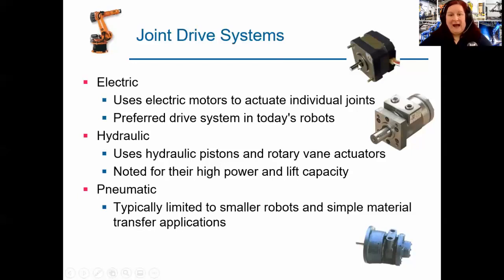So in terms of how we drive our industrial robots, we might have different drive systems. They might be electric, hydraulic, pneumatic. If we are lifting very, very heavy stuff, hydraulic is the way to go. If we want to do something very fast, very abrupt, and many, many times, and it's not really high forces we want to achieve, pneumatic is the way to go.